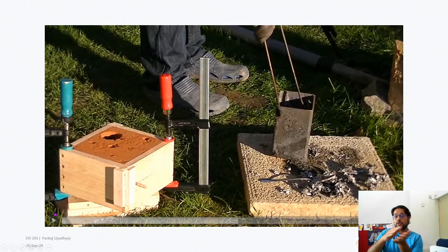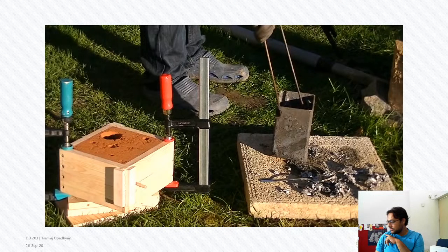If it flows out, then what you get is something called flash. I can show you flash generally in plastic parts. If you observe carefully in cheaper plastic parts, especially in cheap toys, there's a line somewhere in the middle and some amount of plastic kind of comes out. That piece is where the two halves of the injection mold have met, and the plastic, instead of just filling the cavity, has also come out of the gaps between the two halves of the mold. That part is called the flash.